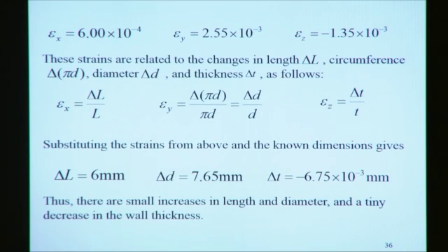Putting in all these strain component values, we can find the change of the length, the change of the diameter and the change of the thickness. It is observed that the change of the thickness is very small in this case as compared to the change of the length or the change of the diameter.